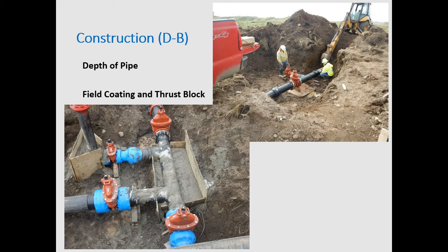So this photo was just to show the depth of pipe, relatively shallow. There are other deeper areas, and the photo on the bottom left shows a casting of the thrust block and then the field applied coating. That's a Viscotac product, and that's what we recommended that they coat in our design build phase. The owner was really hesitant to put any metal in the ground. Unless you have a vault at every one of these, which is really cost prohibitive out here with barge shipments more than 2,000 miles away, it still requires coating. Not that it couldn't be done, but it was just very expensive. We recommended sealing off all metal parts and fittings with that Viscotac product.